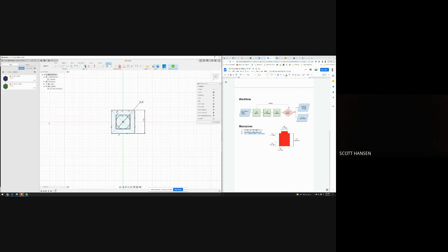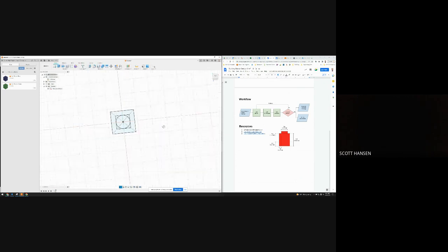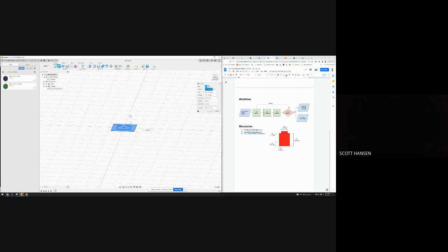And so that is all the features of this block as viewed from the top, which will actually let us create the entire block itself. So let me just rotate around so we can see that. Let's start making this 3-dimensional. I'm going to start by selecting everything and just doing an extrude to make the main body of this block, which we can see is 6 P units. So 6 times 1.6 for my distance.